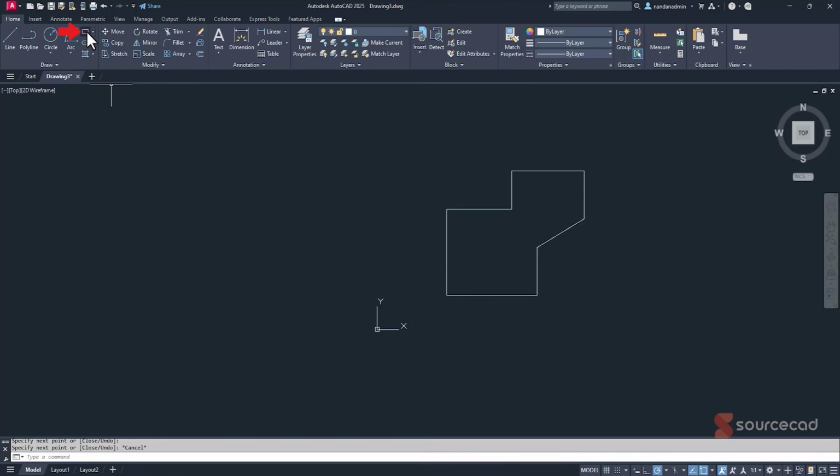And now let's make the second part of this drawing. For that, I'll go to rectangle and I'll just randomly click anywhere inside or maybe even outside this one, and I'll make the rectangle of length 6. So I'll type length is 6, comma, width is 1 and enter. So we have this rectangle of length 6 and width 1.